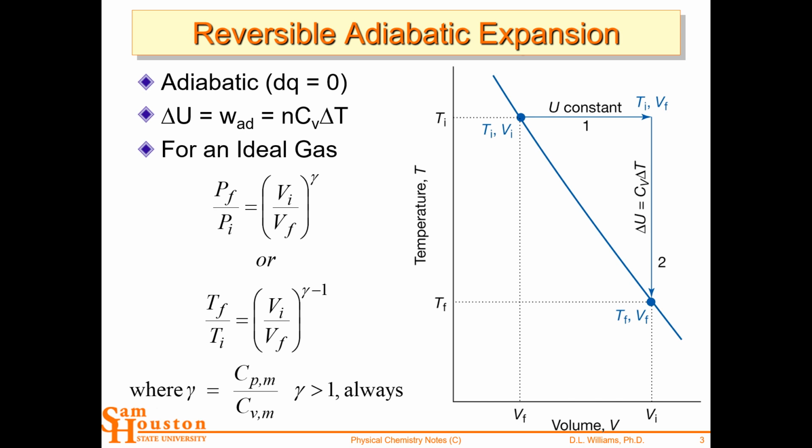Because in this case, all three variables are changing, pressure, temperature, and volume, and we just have a two-dimensional plot, pressure and volume, we need to know what temperature it's going to hit and what that volume is going to be. So a lot of times we're given the temperatures in a Carnot cycle, but we're not given the volumes. Or we're given the volumes and not the pressures. So we have two of the variables, we need to solve for the third. And so that's when we use this gamma.